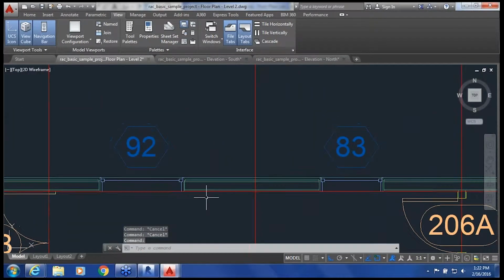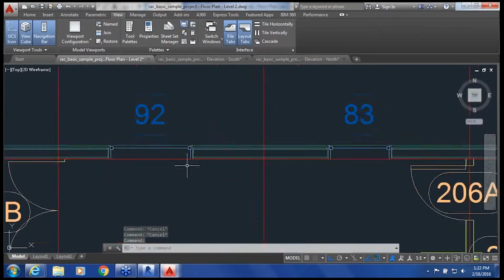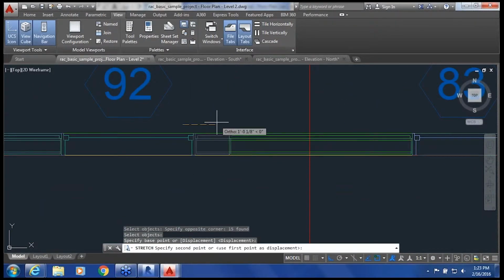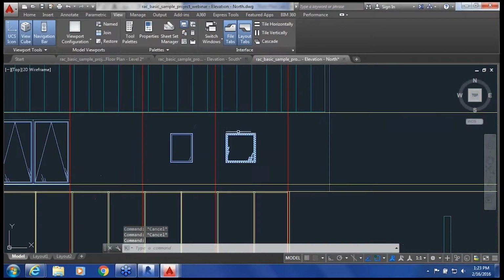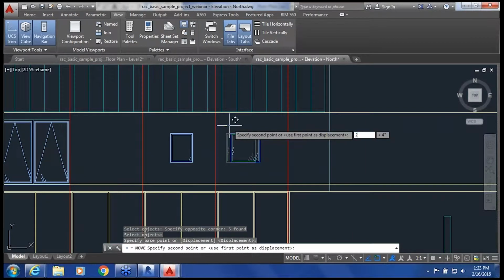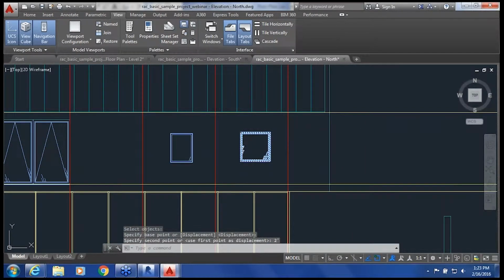So this is what I'm talking about when I talk about that tracking exercise. I've moved my window or my door, or I've changed sizes of said window or door in plan, but I've now got to go to the elevation and make the exact same movement. So now I'm moving something in 2 different places, rather than being able to move it in one place and have it move everywhere because it is a 3D element.